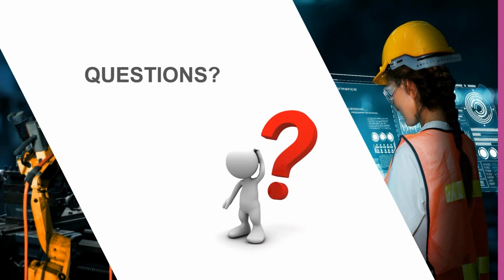Yes, you can export STP, IGS, OBJ with your Freestyle model. In fact, I brought it in as a step file within KeyShot, but you can export it as IGS and OBJ as well, and whatever Creo has available to export, you can export the Freestyle model as such.